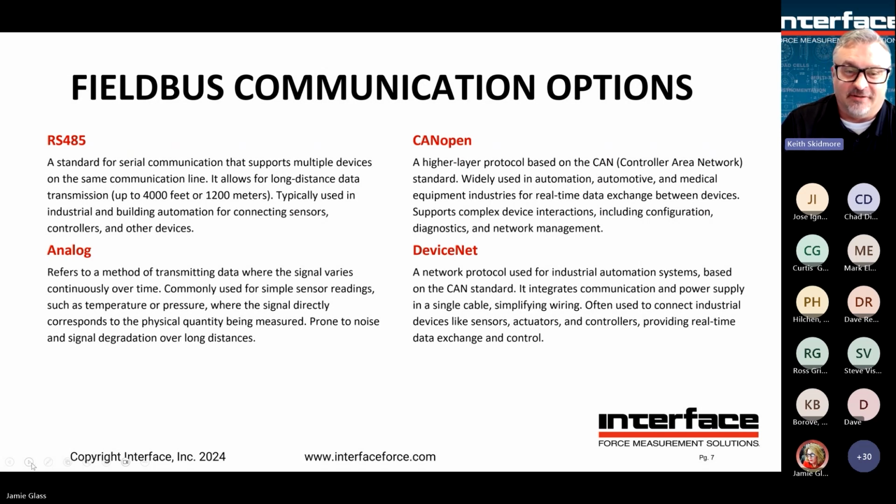We have a list here of various protocols. Again, RS-485 we talked about, pretty common. It has some limitations, but it's widely used. A lot of PLCs and things may have RS-485 serial ports. Analog, and you can always connect analog signals into networks, and that's usually done with some kind of analog card. So it might have, usually, 4 or 8 channels of, say, 4 to 20 milliamps, and then you have a sensor that connects via that module into a network.